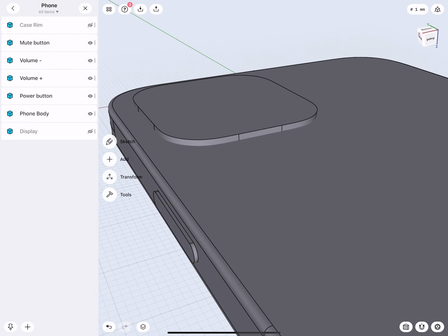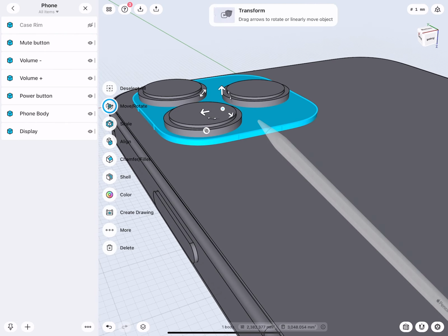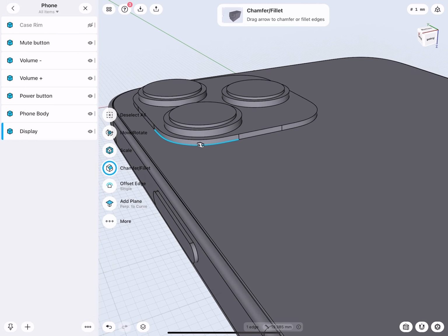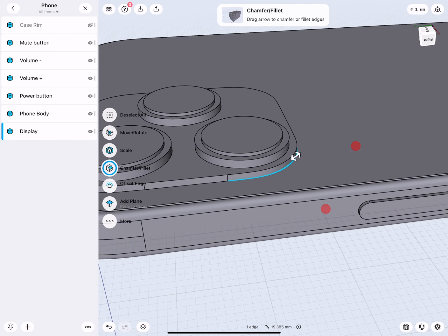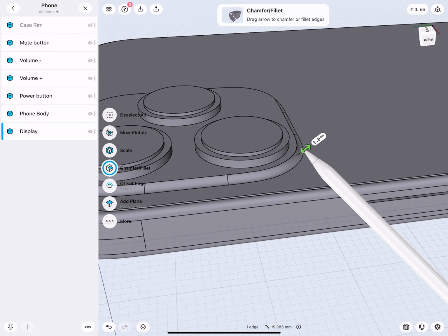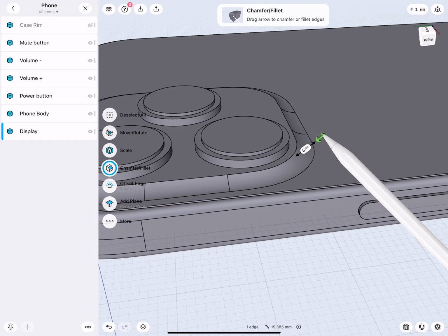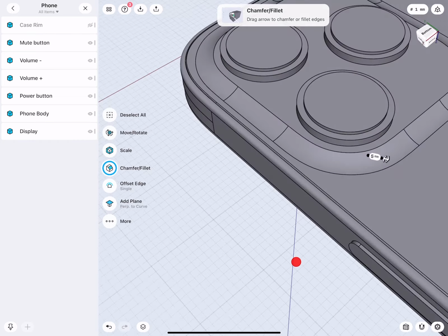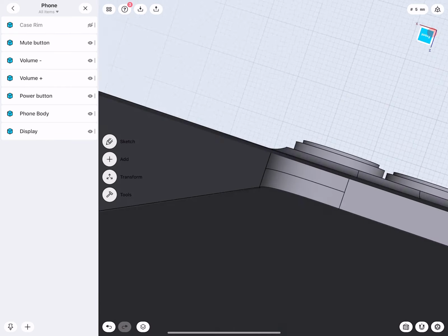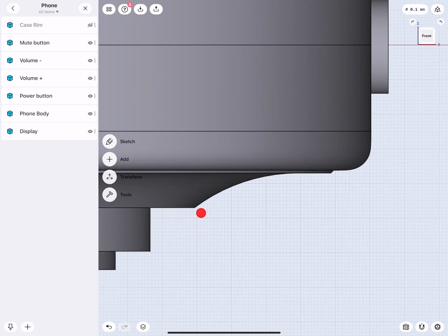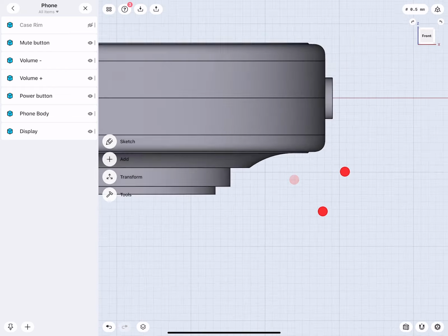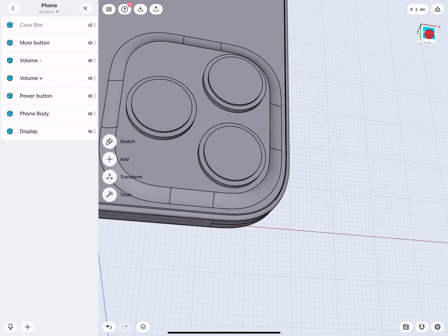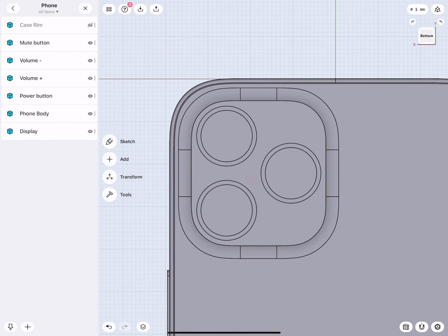Okay, so yeah, this has to be joined to there. Union. Very good. And now I have actually this corner down here. And this corner I can fillet. And when I start pushing the fillet, you see actually how this gets wider and wider. Instead of being just a quarter arc, you can see how this looks more like an ellipse. So that's the way how you actually do that particular edge rounding.